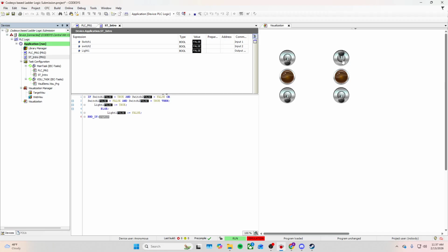Now, overall, you can see that switching either switch 1 or 2 will affect the state of the output. But overall, if they are in opposing states of false or true, the light will be operating properly. This proves that either input changes the match versus mismatch condition and flips the output, which is exactly the XOR behavior described in the program logic.